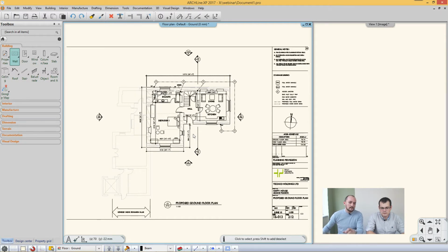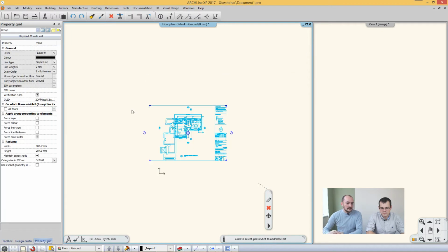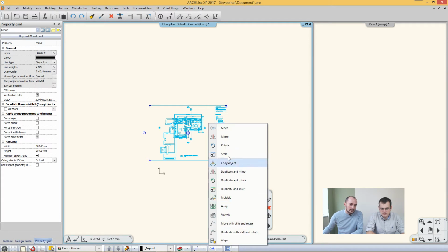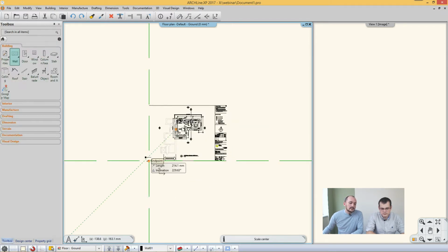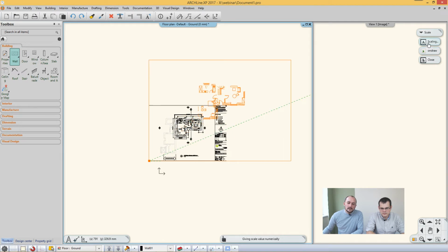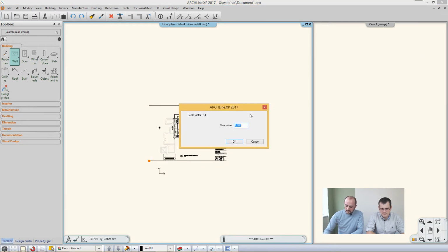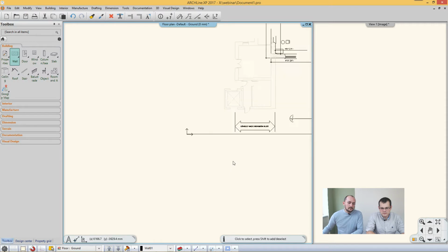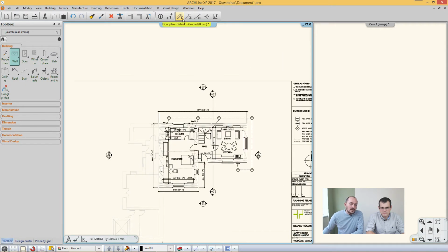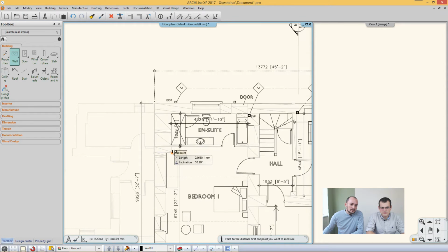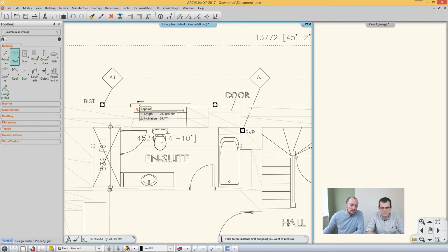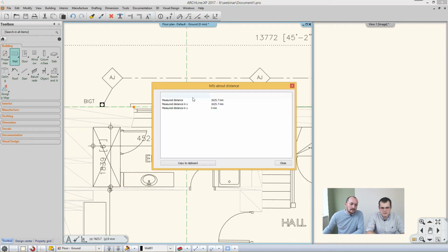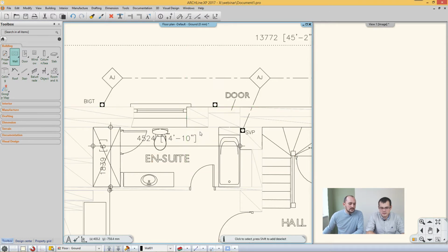You just undo this step, then you select this whole drawing that you have imported, and there is the scaling here. You can set up the scale, you can set up the scaling origin, and you can even set up the scaling value, which I think should be 100 now. I didn't check the values, but if I scale it up to 100 and then check this value here, maybe let's just go with this window width, we can easily tell that this is realistic. Should be good, yes. So this is good.